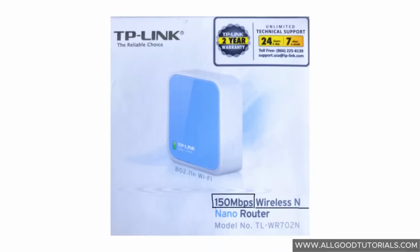Now, to understand what data rate you can achieve when you're in good RF environments, such as close to the access point, not moving very much, versus what you can achieve in more difficult RF environments, such as on the cell edge, you need to understand these data rates that are described on your product's packaging. Typically, and when I say typically, I can't think of one example where this has not been the case, the data rates that you see advertised for your product will be the maximum data rates that are achievable if you're in good RF conditions.